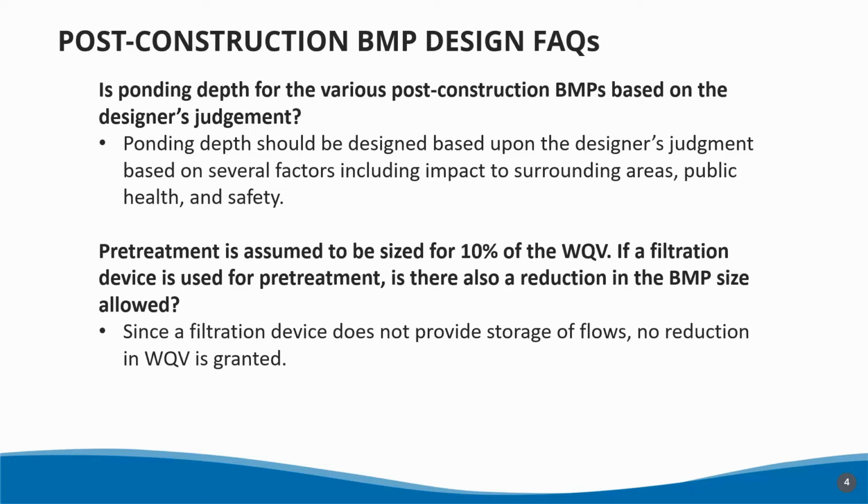If it is going to be located adjacent to another facility or something that's susceptible to ponding or flooding, definitely have an overflow system, some way to discharge flows if they reach a certain level. There are also other options if you want to minimize the ponding or make the BMP larger, with a larger surface area. Those are all considerations that need to be made.